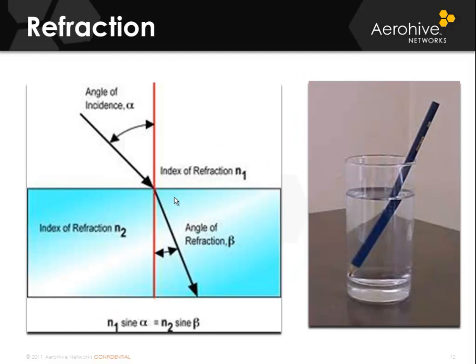Refraction. Refraction is when the signal is changed in direction due to passing through a different type of medium. A good definition of this is the bending of a signal as it passes through a medium with a different density, causing a redirection of the wave. RF refraction most commonly occurs as a result of some atmospheric condition. The three most common causes of refraction are water vapor, changes in air temperature, and changes in air pressure.